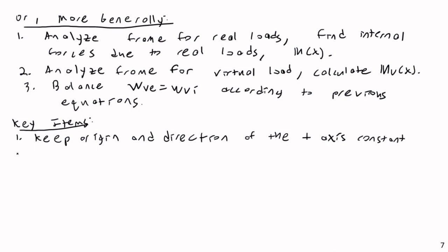2, as always with these, what is a common way people usually screw up? Units. Yes, watch your units. If you're using English units, I suggest that the first thing you do right off the bat is convert your length to inches.